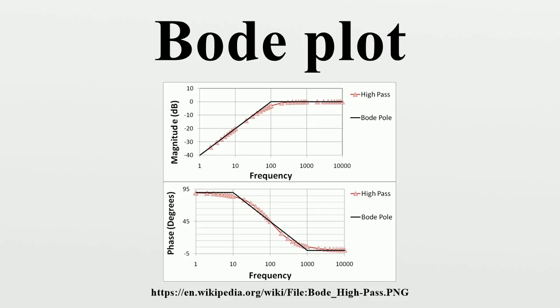Definition. The Bode plot for a linear, time-invariant system with transfer function consists of a magnitude plot and a phase plot. The Bode magnitude plot is the graph of the magnitude function of frequency. The axis of the magnitude plot is logarithmic and the magnitude is given in decibels, i.e., a value for the magnitude is plotted on the axis. The Bode phase plot is the graph of the phase of the transfer function in degrees plotted logarithmically as a function of frequency.